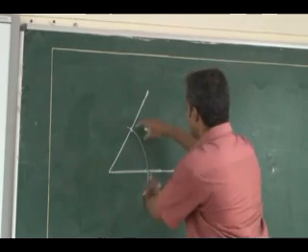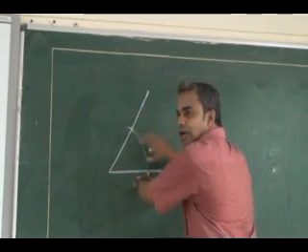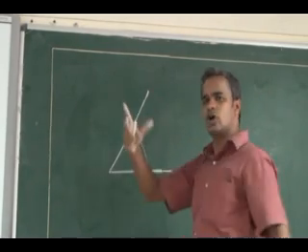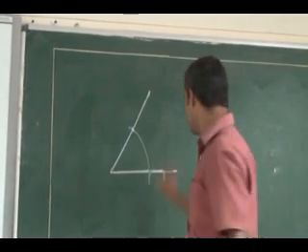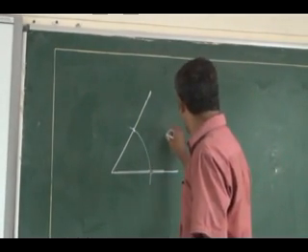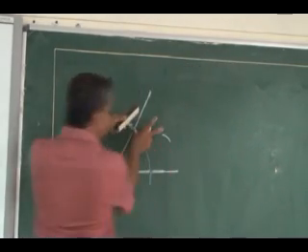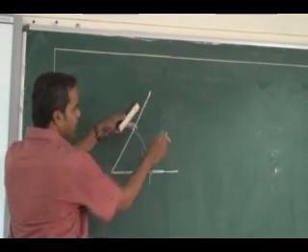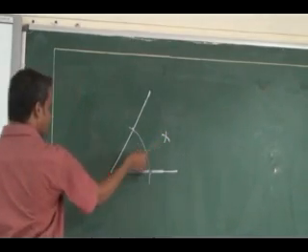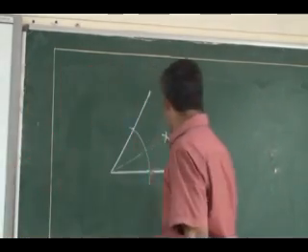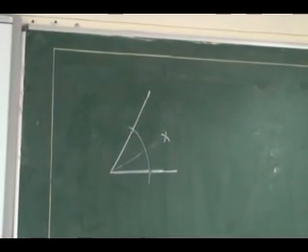From these two locations, I can take more than half of this arc length. That is an arbitrary one. You can take more than half of the arc length with the compass. From here I can draw an arc. I need not cut it here. From the other end, with the same measurement, I can draw an arc here. It will intersect. Now by joining this to the center, it will divide the angle equally. Whatever angle you have, it will divide it equally.